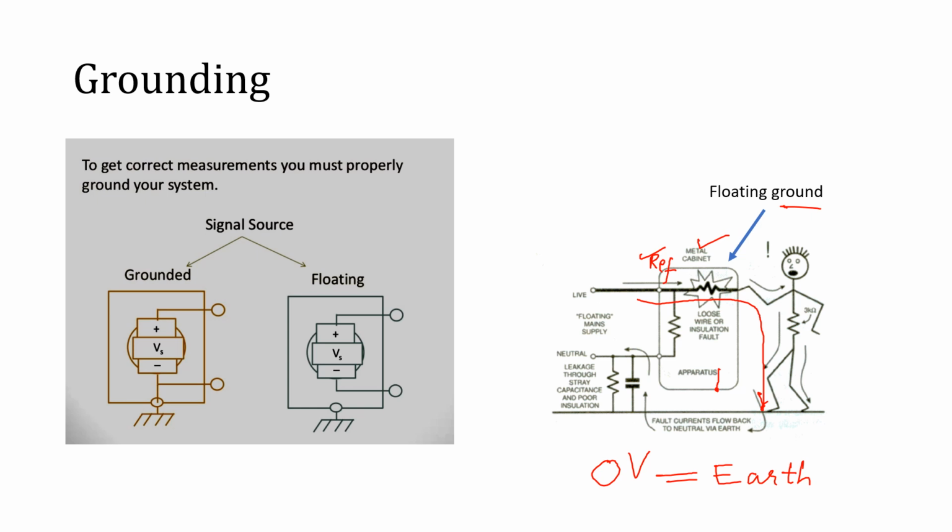So in this diagram it is explained what the best way is. When you have the device with its own circuit, where the current return is there, very good, negative and positive are connected properly, the circuit will work. But when you forget to connect this reference to the absolute reference, there are many chances of floating ground and of a human getting an electric shock, and there are other disadvantages of current surge, high voltage and other noises. So it is always better to properly ground your interfacing circuit with the absolute ground.